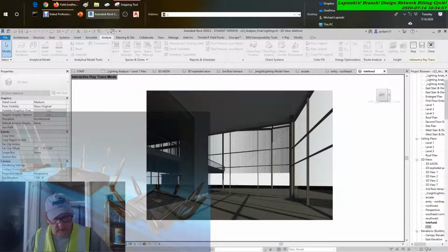Now, the conceptual types dialog box allows you to add the assumed values of building elements for the mass form. Schematic types. The schematic type dialog box allows you to edit the assumed values of the U values for each building system. Here's where you can customize the assumptions for the building type for insulation values as shown.